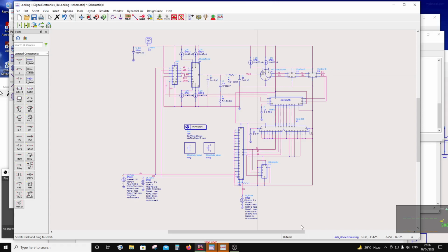Another one which I have done, which I'm going to present in the next session, is a 40 gigahertz PLL using 130 nanometer. Right, so this one is using 7 nanometer. It doesn't have a complicated divider, right? But when you use 130 nanometers and try to achieve 40 gigahertz, then you have injection lock dividers. So in the next session, I'm going to present those injection lock dividers and the entire loop, in the same fashion. And then maybe if I have computing resources, I will show you the phase noise of the PLL. But right now, I'm not geared up for that.